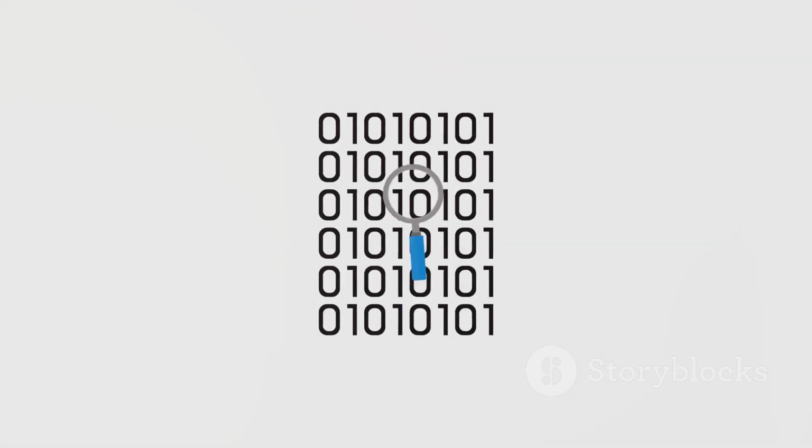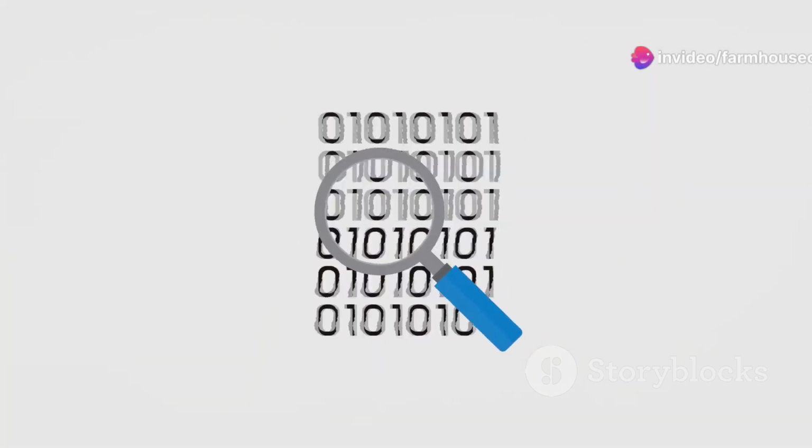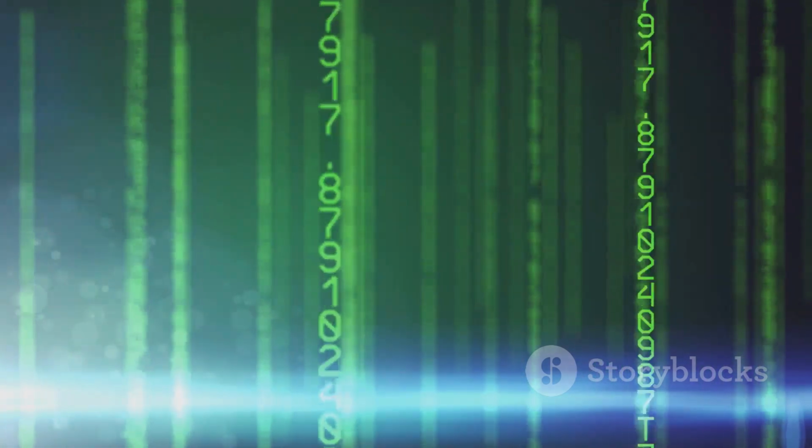We label the rows and columns with input variable combinations, following gray code to ensure only 1 variable changes between adjacent cells. Gray code is particularly useful because it minimizes the chance of errors during the simplification process by ensuring that only 1 bit changes at a time.